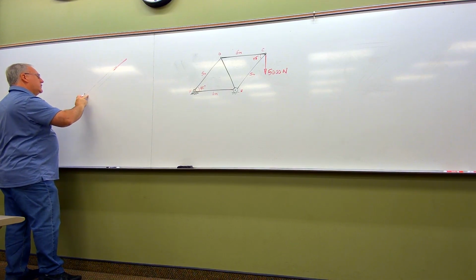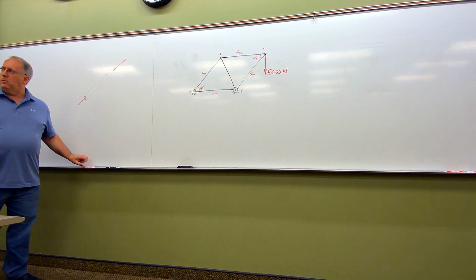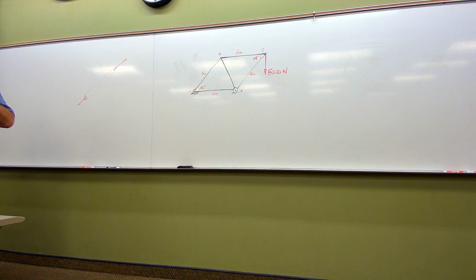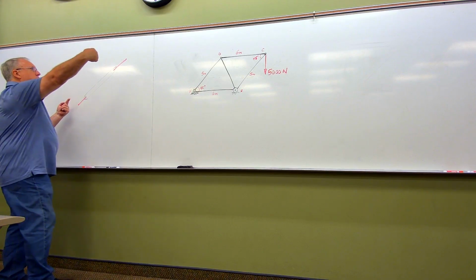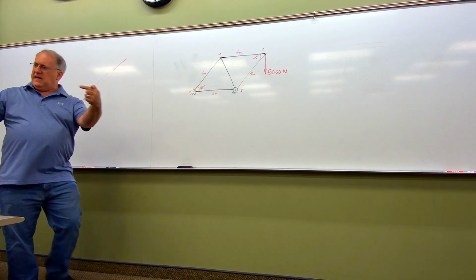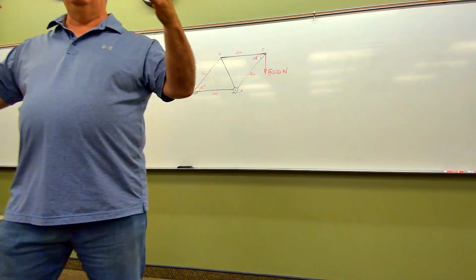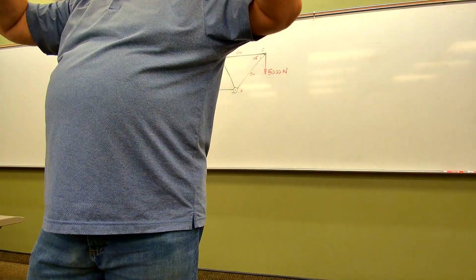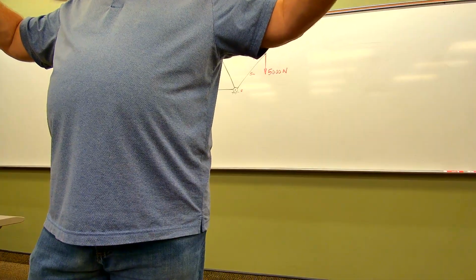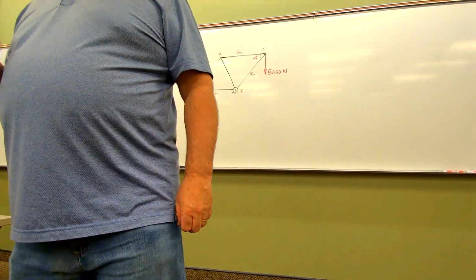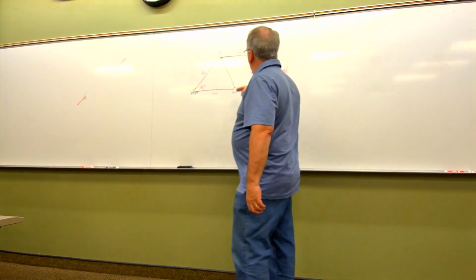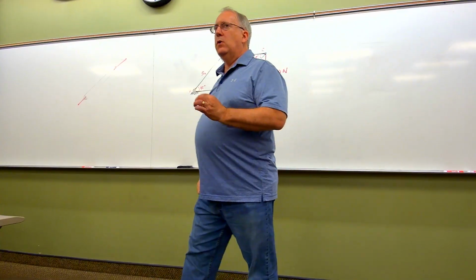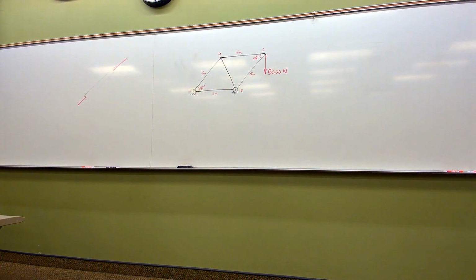Let's also remember that those forces, depending upon which way the arrows are pointing, will create either compression or tension in the two-force member. So if I had forces pointing in on the two-force member like this, they're trying to compress, squeeze together that member. On the other hand, if my arrows are pointing away from the member, then those are trying to pull the member apart. That's tension. All right? Because of that, and going along with the same idea, whatever forces are occurring in these members here, those forces can only be causing tension or compression on the member.